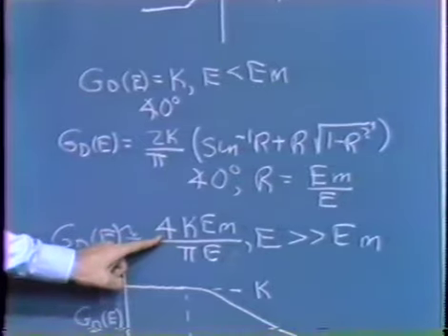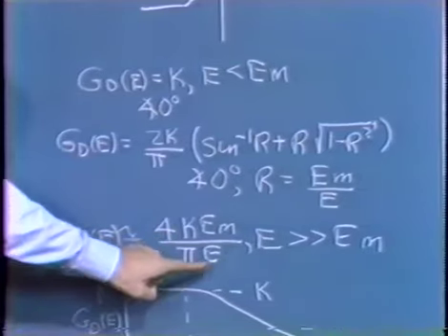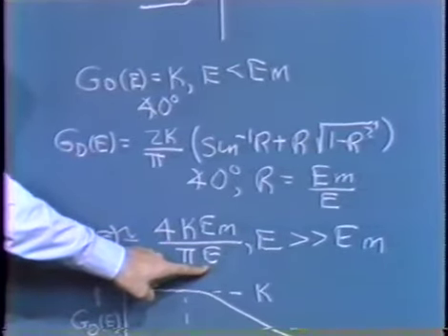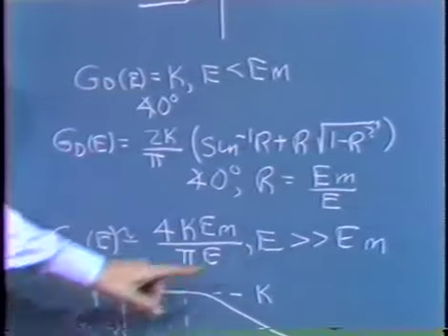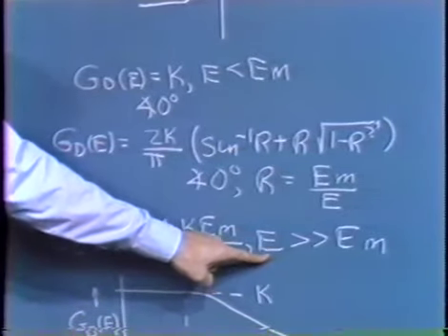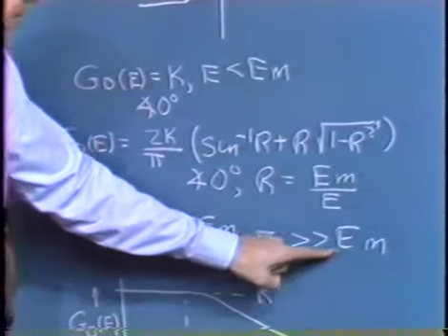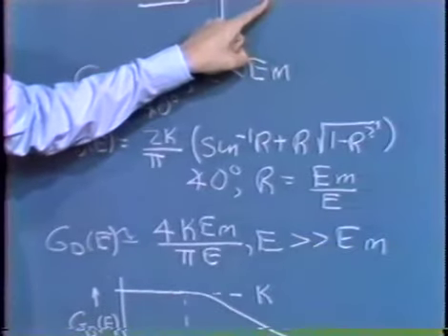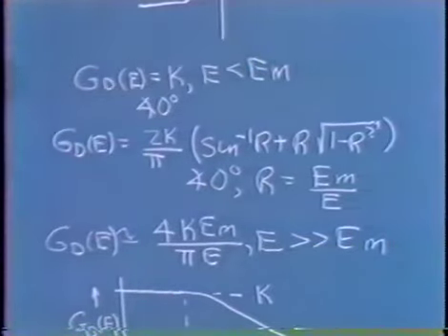So that's the magnitude of the output fundamental. We divide that by E to get our describing function, and that's in the limit where our test signal amplitude E is much, much larger than the value necessary to saturate the element.